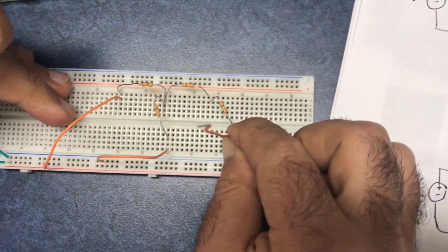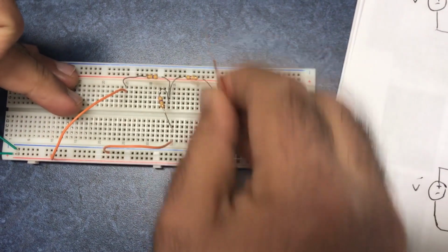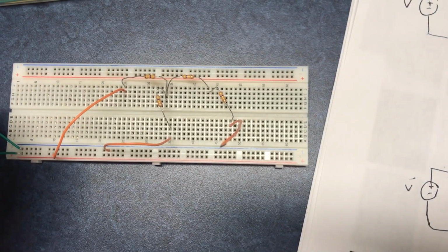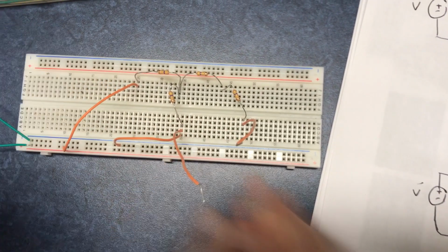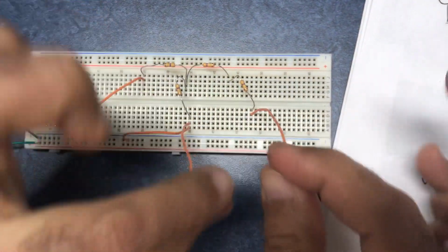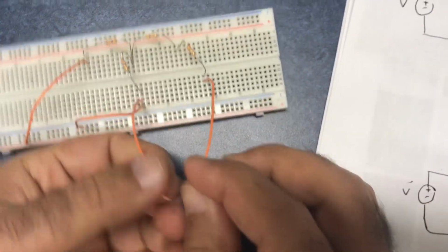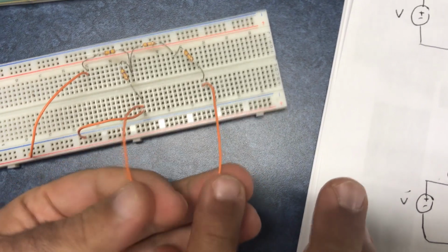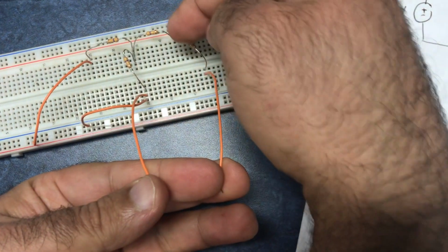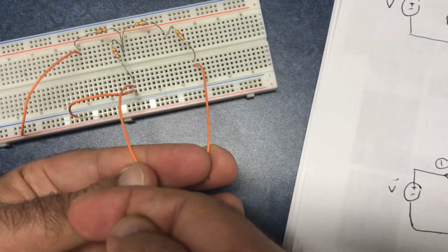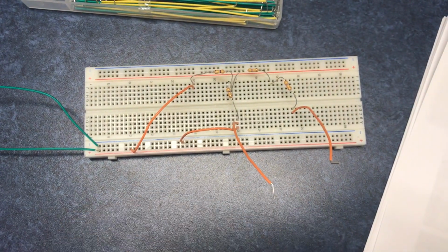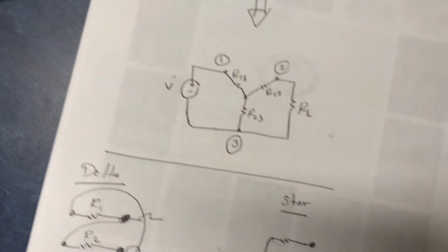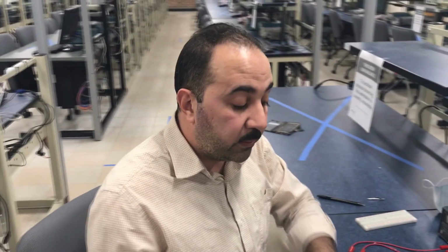Imagine that these two connections are representing my ammeter. So I will put one here, and the other one is connected in this. At that time, what I'm seeing, these two, I'm plugging my ammeter here. So my ammeter is connected between these two terminals. The current is going from this to my ammeter and then going back to the circuit. This is what's needed for that lab. Please don't forget to take a picture of everything before leaving.